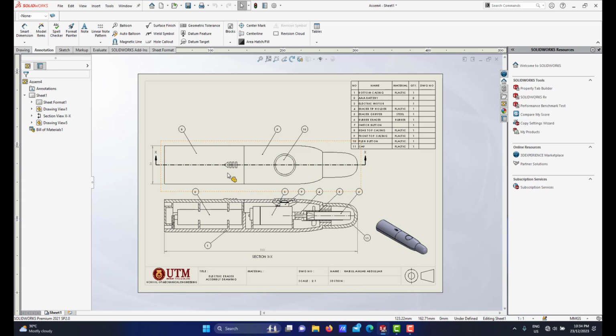All right, to do the exploded drawing, if you look here, this is a drawing I have already done, but this is the assembly drawing. To do the exploded drawing, if you look at the bottom here, we have Sheet 1. I can duplicate it, so I don't have to do the BOM again. I just make a clone of this assembly drawing. I bring my mouse here, right click, make a copy first. Then I bring it here again and do paste. After selecting, I just click OK.